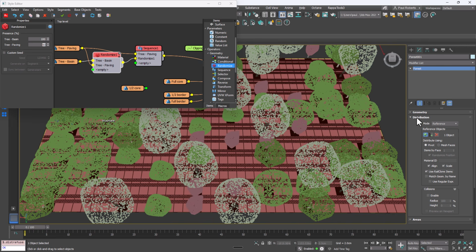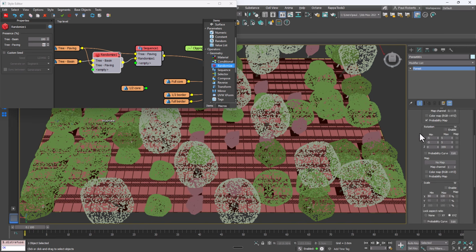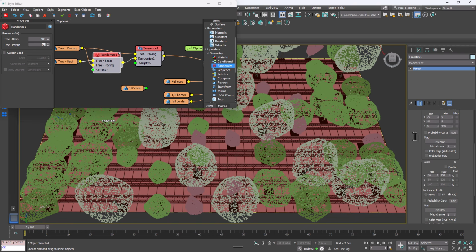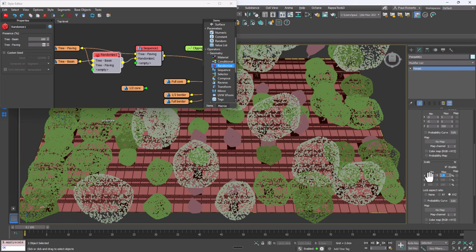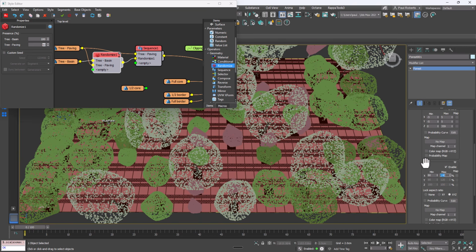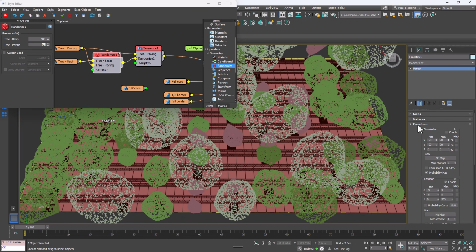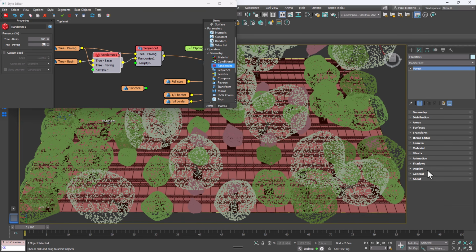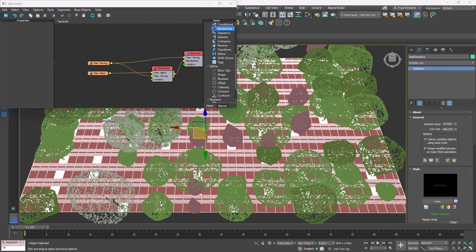Forest enabled. The trees are now positioned correctly, but we can also introduce some variation to make the result look more natural. To do that, open the Transform rollout and enable Rotation Randomization and Scale Randomization. You can adjust the settings to suit the trees and the amount of variation that you want. And that's all that's required to target ForestPack geometry onto the selected RailClone segments.